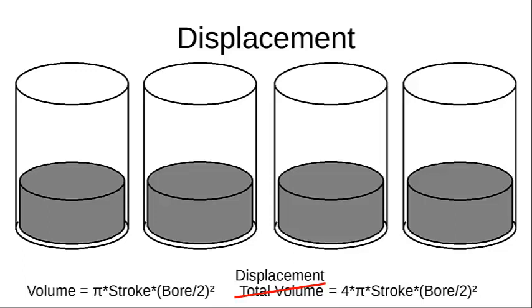You hear a lot about this in engines. You say 4.2 liter, 4.8 liter, 5.3 liter. That's what it actually means. Here we happen to calculate it for an inline 4, but the same formula and methods you use to calculate it for other engines. The Mustang, the 4.2, 5.0. That's essentially what it means. So displacement is nothing more than volume.